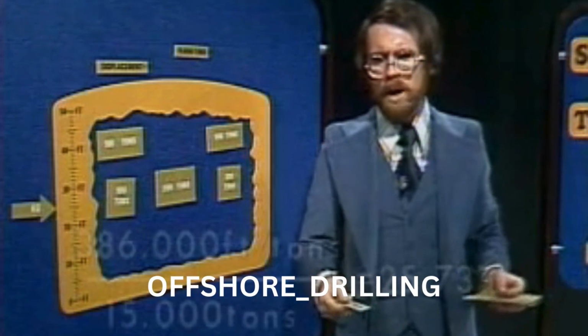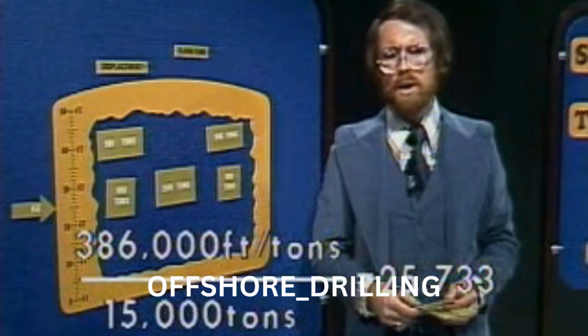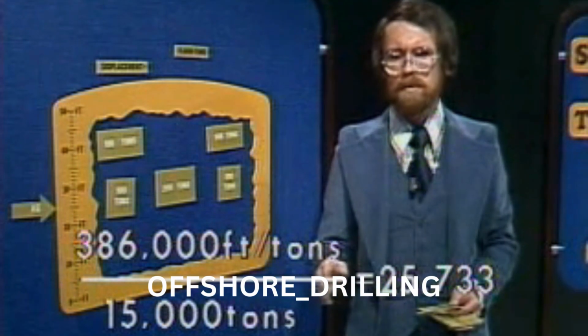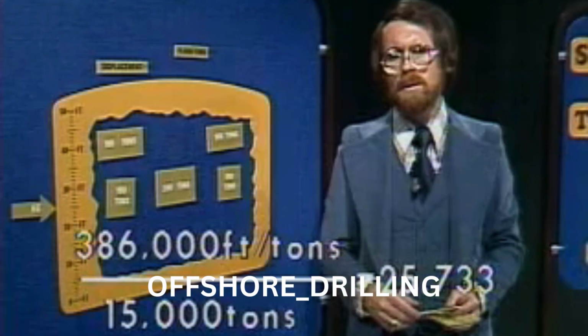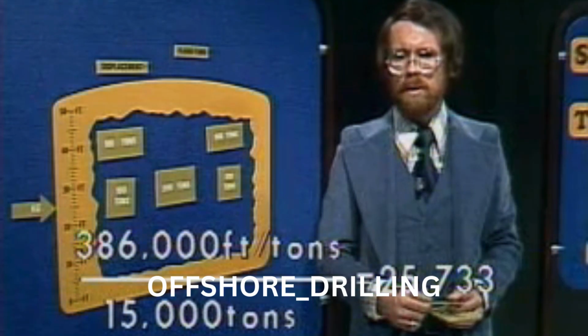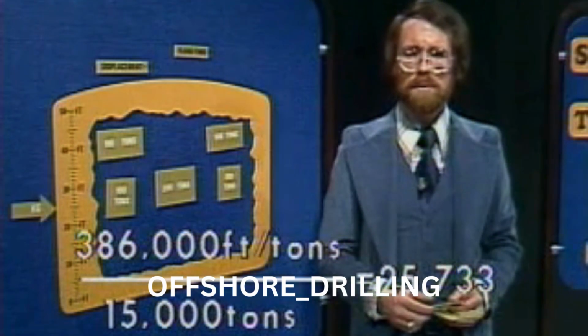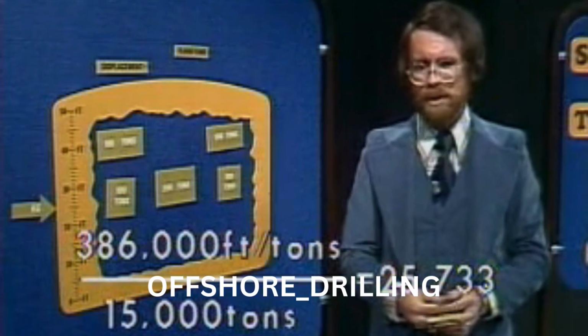Now, if we divide 386,000 foot-tons, the final moments, by 15,000 tons, the final displacement, we get 25.733 feet, which is the new kg.